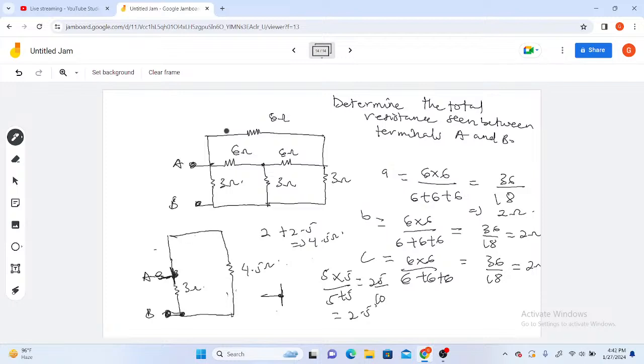And at this point, you can clearly see that there is a node here. Though there is no branch here, once this third one is meeting this, there is a form of T junction here. So this becomes a node. Likewise, this becomes a node. Hence, the presence of a node between two resistors doesn't make it series, but it can make it parallel. Now let's traverse through their paths. They are the only two resistors in this loop. We can conclude that the 3 ohm and 4.5 ohm resistors are in parallel.